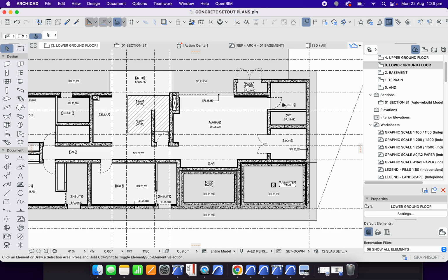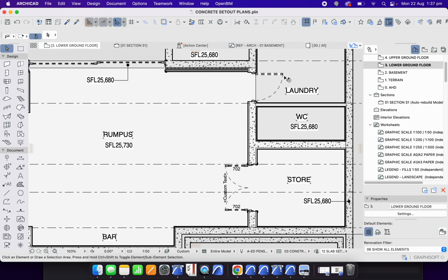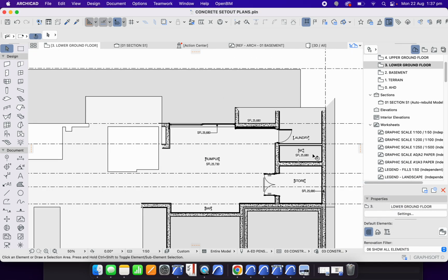We can also see, we talked about before, that the doors have been significantly simplified. So if we change the model view options to say construction, we'll have a lot more information that shows on these. We can also change the graphic override. So one graphic override here is changing the doors so they're showing as dashed. If we change that to construction, we see that will also change.